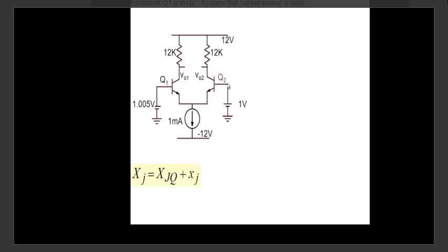Because we said in a differential mode amplifier, the input could also be a DC. So when I say DC value of collector current, we recognize that both these voltages I've applied to the inputs are also DC. The DC value of collector current here will have a bias value plus a differential mode value plus a common mode value, because there is a signal attached here. These are signals for us, so we'll have a differential mode and a common mode.